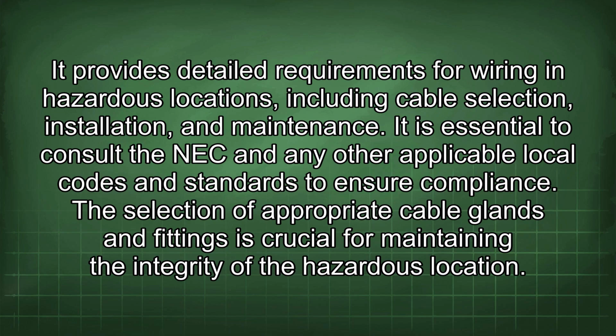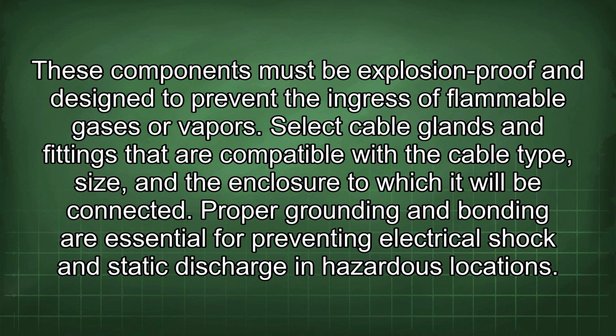The selection of appropriate cable glands and fittings is crucial for maintaining the integrity of the hazardous location. These components must be explosion-proof and designed to prevent the ingress of flammable gases or vapors. Select cable glands and fittings that are compatible with the cable type, size, and the enclosure to which it will be connected.